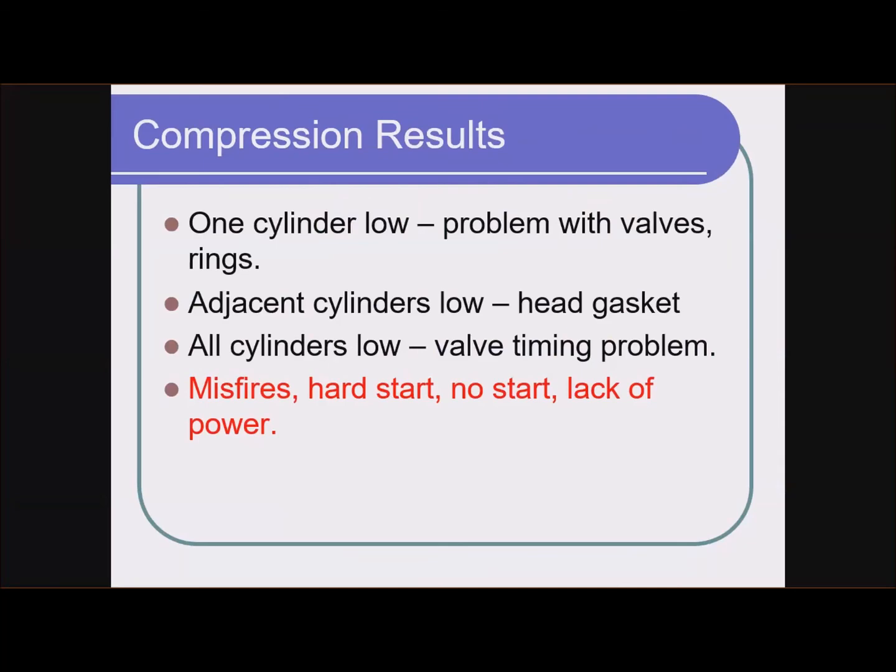But if you're here, then you've probably eliminated spark and you may have eliminated fuel already. So you're looking for something, and you know what you're looking for. If it's a hard start or a no start, you're looking for low compression across the board. Same with lack of power. If you're looking for a misfire, then you're thinking that compression is low on one cylinder possibly, and that's what you're looking for.